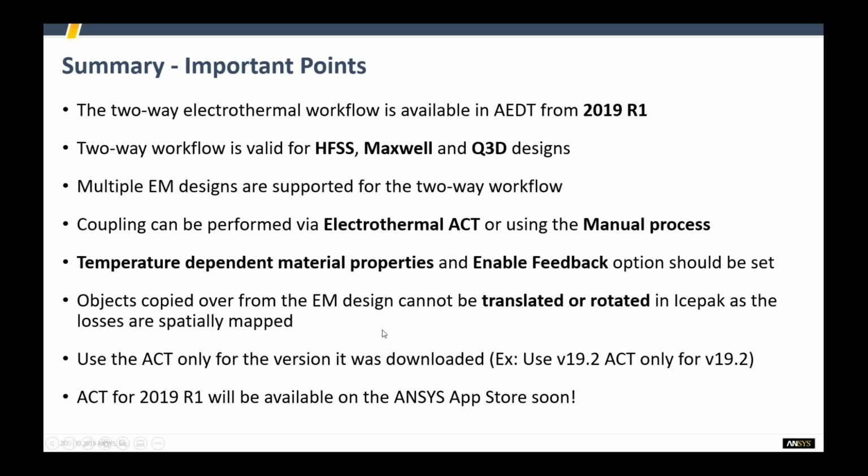Objects copied over from the EM design cannot be translated or rotated in ISPAC as the losses are spatially mapped. So that's one thing we didn't explicitly mention in the previous slides, but good to keep in mind. You can't do any sort of CAD operations after the EM designs have been done.